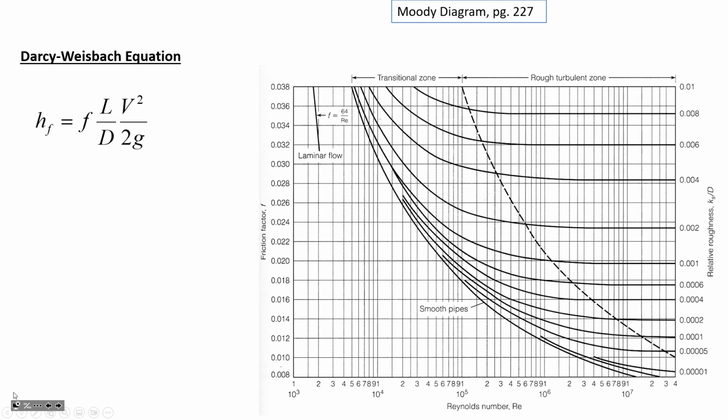All right. Moody diagram. You've seen it, you've used it, you know it. We use the Moody diagram in order to identify the friction factor, F. Now, the Darcy-Weisbach equation is what we use to estimate the effect of pipe friction. So if we're using the energy equation, and I'll write it on the board because we're going to refer to the energy equation a couple of times today.